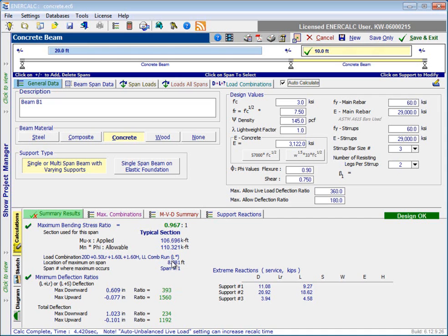But coming back to this load combination, I'd just like to point out this nomenclature that's used to define the live load that's used in this particular load combination. We've used the option to skip load the live load on this multi-span beam, and so this is indicating that for this particular run it's the one that uses live load that's applied to the left span, but it skips the live load on the right span.